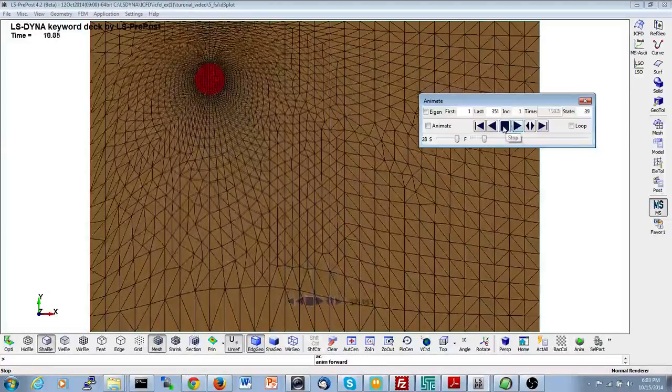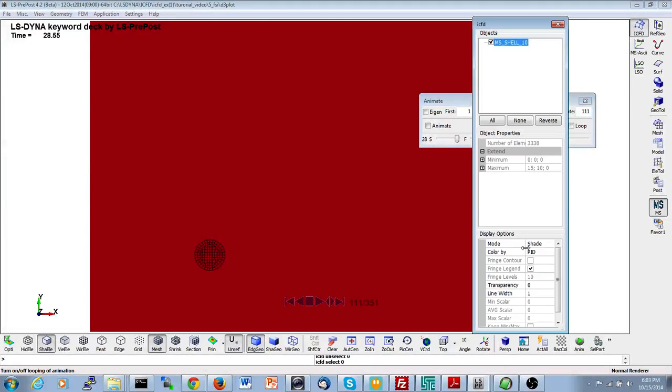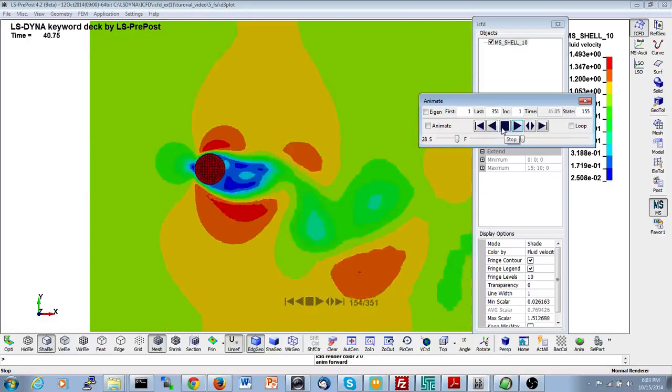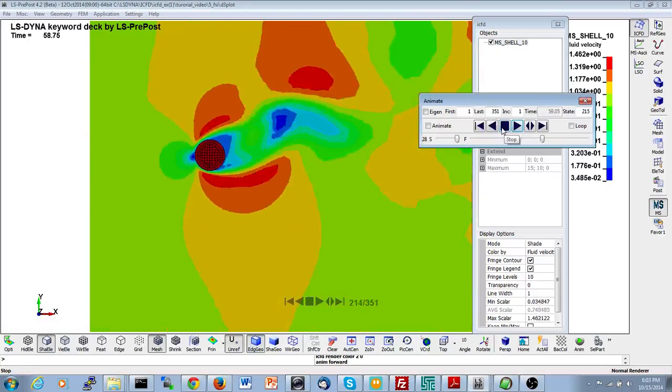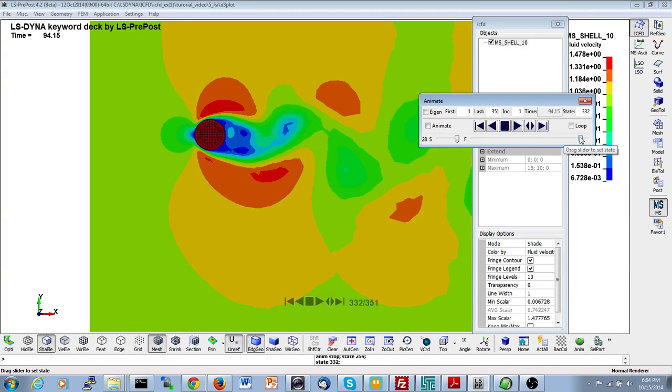So if I do something like this, I get, as a result, something like that. When I animate here, and if I display the velocities, I can see that the fluid still takes into account the solid's movement, but if I look at the solid, it only translates in the y direction. There is no movement in the x direction. This is because the fluid now no longer has any influence on the solid. This would be a coupling direction 1.